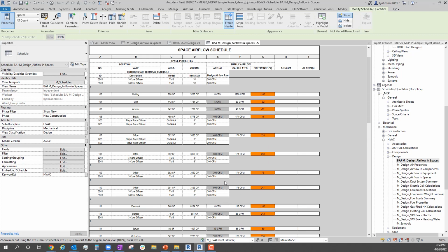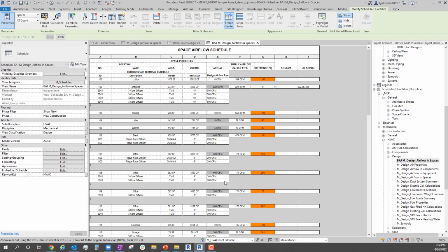So to kind of close up shop on what do I really want this for? How many times do you go into a working view inside of Revit, place those air terminals and give it a value each time, where you say, well, I think these are 125s and there's 4 of them in the room. So you place one on the ceiling, face-based, and you copy it 3 more times and do a fitting of where you think those actually should go, whether it's over desks or over tables or around things or whatever it might be. Getting the placement right is part of the battle. Getting the CFM right is the next battle, right?